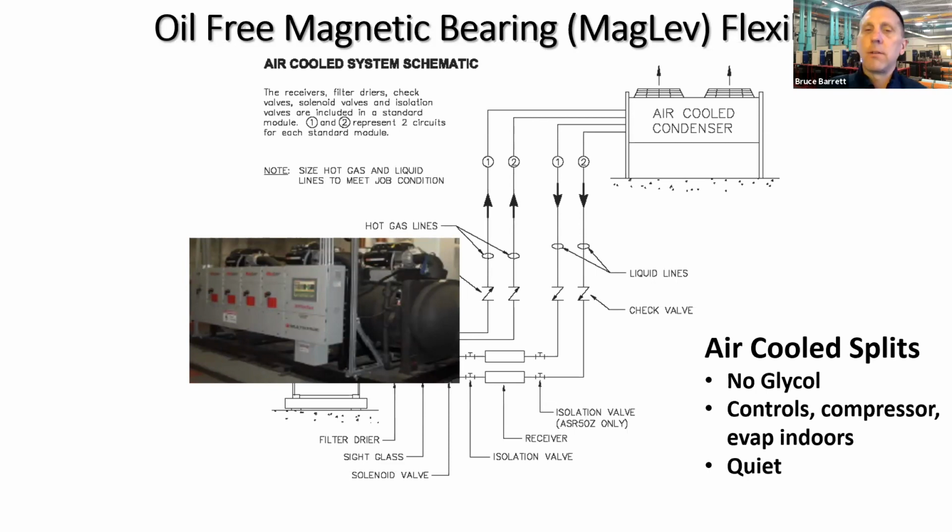Why do people do splits? They want to eliminate glycol from their system. That's number one. Your efficiency can go up 10, 15% with a 30% reduction or no glycol applied. Again, it's a very, very quiet indoor chiller, very quiet outdoor chiller.